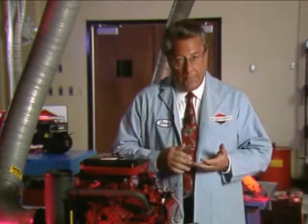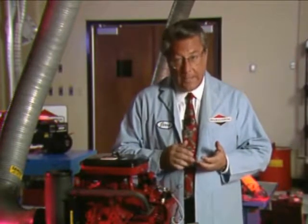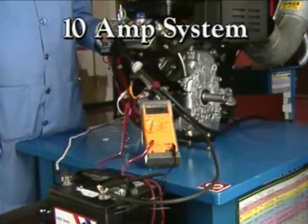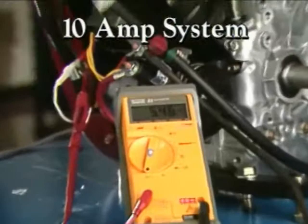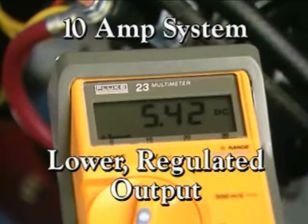Second, the output of the regulated system, in most cases, will not match the rating of the system. Example, when testing the output of a 10-amp regulated system, the reading may be as low as 4 to 5 amps because the regulator will only allow sufficient output to meet the electrical needs of the battery.